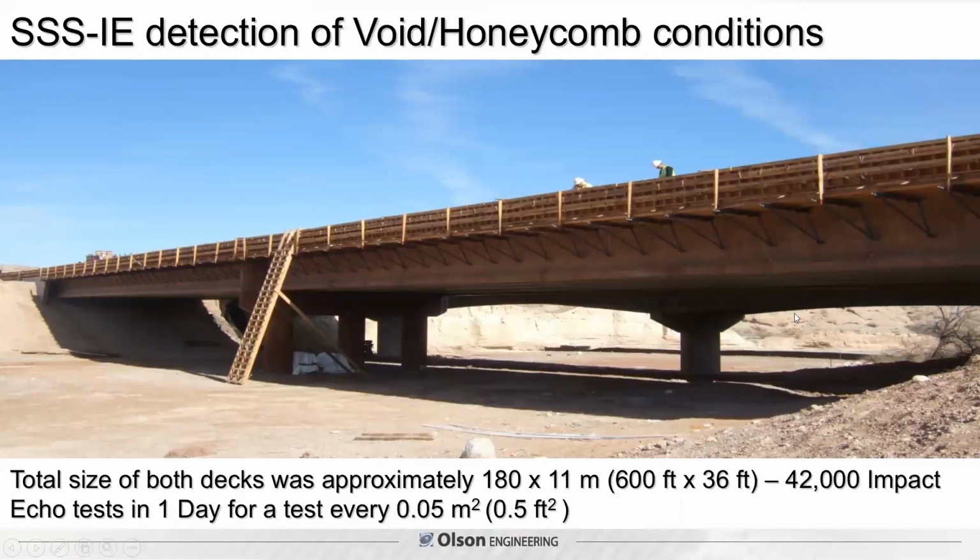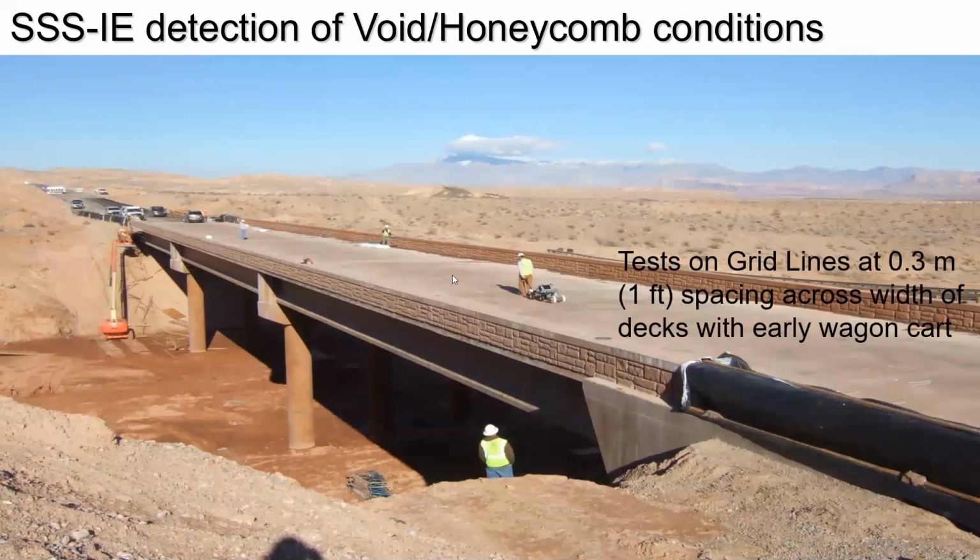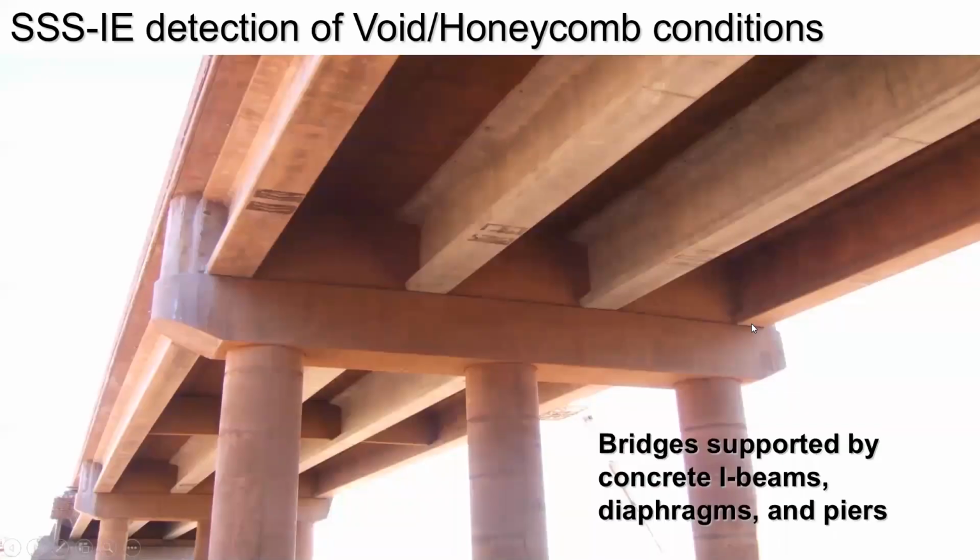So this project had 2 bridges, 600 by 36 feet, brand new bridges. They scanned with 42,000 tests in 1 day, a test every half square foot with a 1 foot spacing between the wheels. It was done because they were quite concerned. It's in the desert Southwest near Las Vegas, but the concrete was a couple hours out of town. It set up and had a lot of drying cracks, surface drying plastic shrinkage cracks, that were of concern that maybe the concrete wasn't well consolidated. So we tested at a 1 foot spacing in grid lines on these 2 bridges. The deck was also well coupled to the underlying diaphragms and girders at the piers.